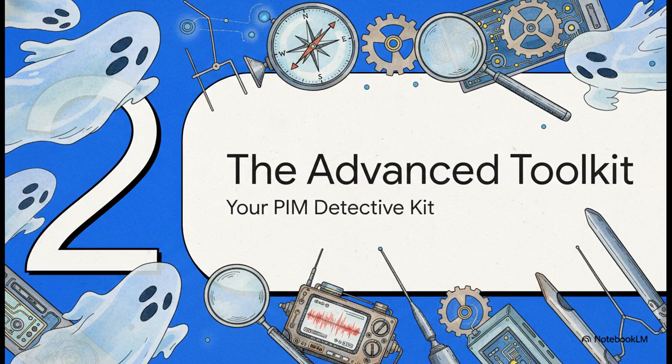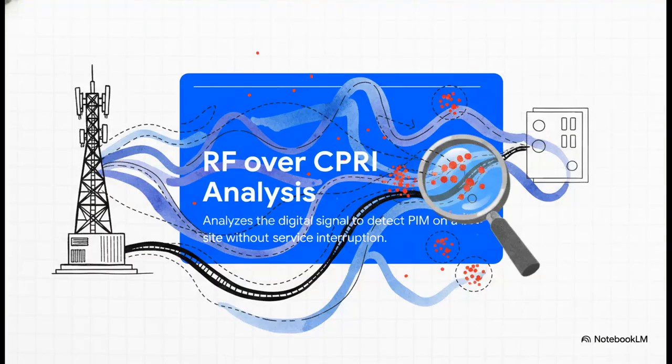So how do you hunt these ghosts? Well, you've got to upgrade your gear. Think of these next few techniques as your specialized PIM detective kit. It's designed for those super complex investigations where the usual methods just won't cut it. First step in the kit is a real game changer, RF over CPRI analysis. Instead of having to take a site completely offline to test, this technique lets you tap into and analyze the digital signal that runs between the baseband unit and the radio head. You can actually see the PIM as it's happening on a live, fully operational site.